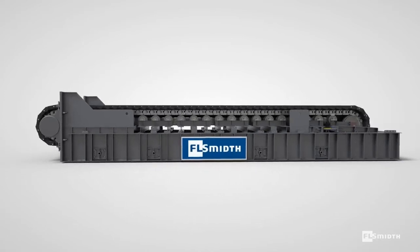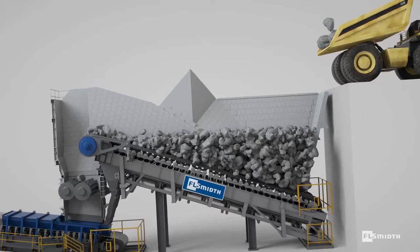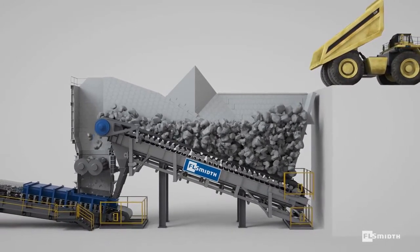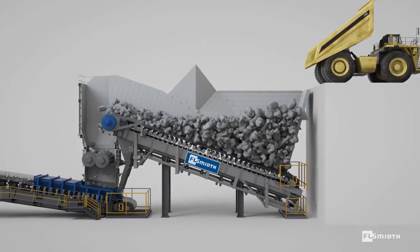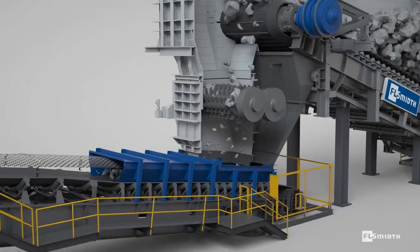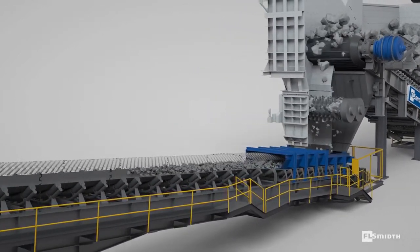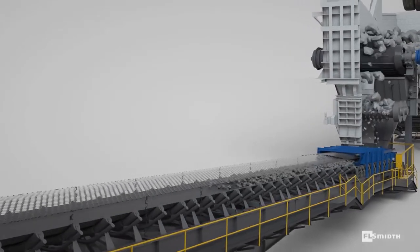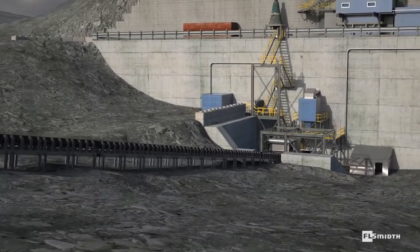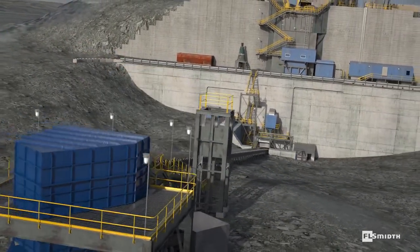Apron feeders can be installed horizontally or at an incline prior to any crushing or sizing, as they withstand the high-impact forces from large run-of-mine material as it is tipped directly from mining trucks. Acting as an interface between mining trucks and the processing system, apron feeders provide steady, controlled feed for downstream processing, improving plant efficiency, increasing product output, and wear parts service life.